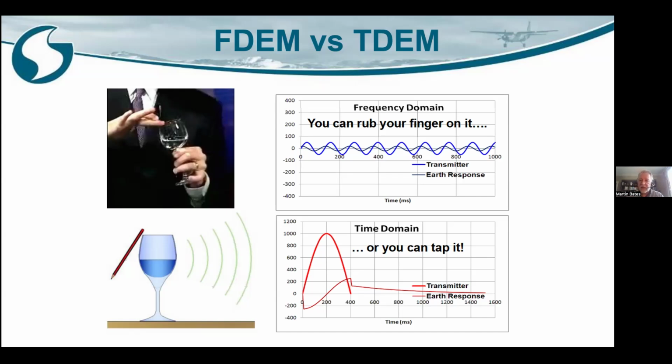And if you run at a slightly lower frequency, it will penetrate a bit deeper. So we run with four different frequencies, which gives us a bulk resistivity for the nearest few meters, then another 20 or 30 meters, and another, and then eventually down to 120, depending on the conductivity of the material that we're flying over. So we're getting a change in bulk resistivity with depth. So we've got structure in the near surface, which we can figure out. But because it's a weak signal, it doesn't go very far beyond that. So it's a really good near surface method.